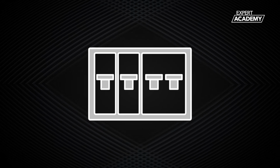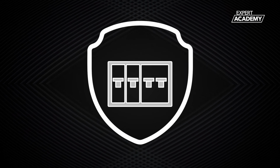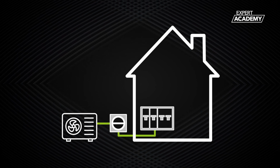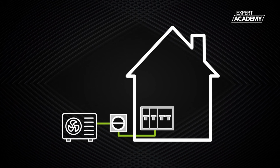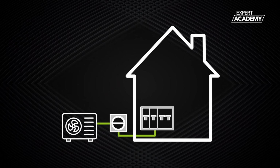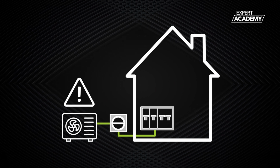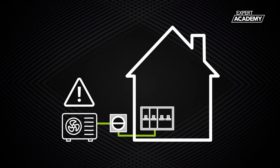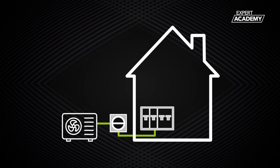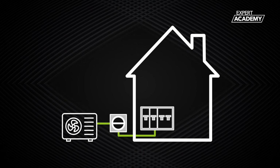Another important electrical consideration for a heat pump installation is the selection of the appropriate circuit protection. These will be located in or alongside the main electrical panel for the property. Generally, an electrician will need to confirm the specific type required along with the heat pump manufacturer's instructions. If the wrong type is selected, either nuisance electrical interruptions, otherwise known as tripping, can occur, or the unit's electrical components are not adequately protected. The circuit protection safeguards both the property and the electrical circuit from overcurrent or short circuits.